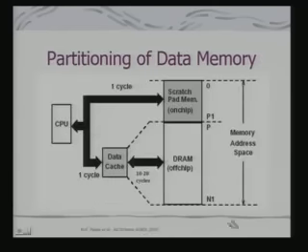If we look at the memory map of the processor, this is a complete memory map, and the scratch pad memory is basically on chip memory, and we have seen that different processors have different amounts of on chip RAM. So, we can think of these in terms of a scratch pad memory. This DRAM is typically off chip memory, which occupies a portion of the memory address space of the processor, but it is typically resident outside the chip.